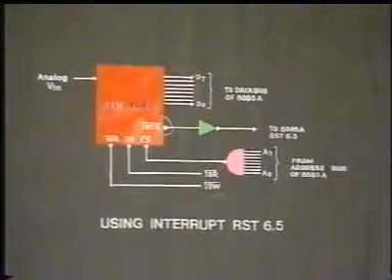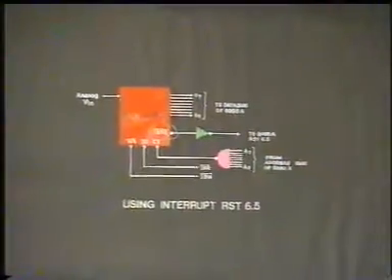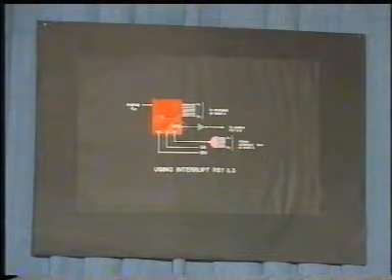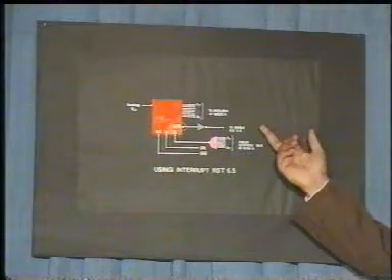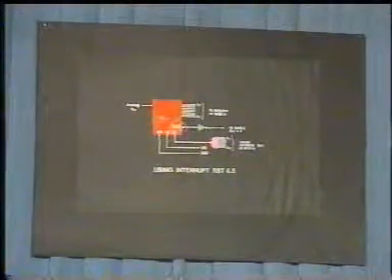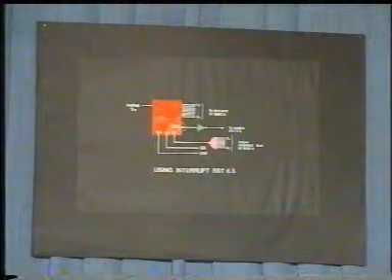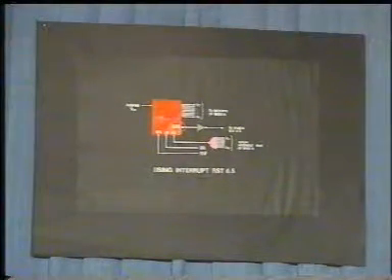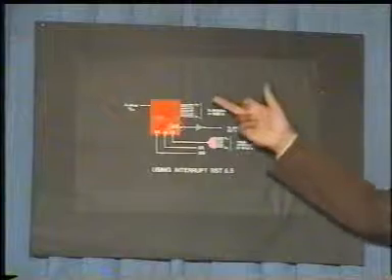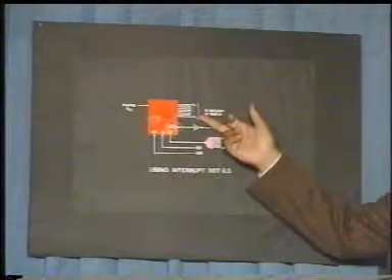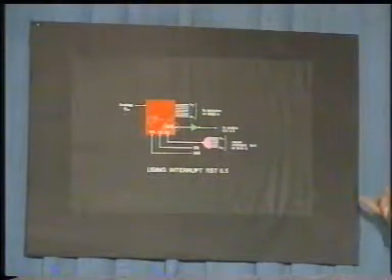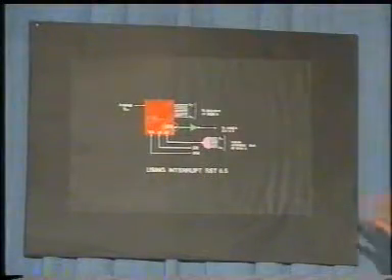If the microprocessor interrupt system is enabled, although we have not discussed the interrupt system as yet in detail, but I'll take it to the minimal level. Whenever the interrupt is recognized, the microprocessor will invoke the interrupt service routine to read the digital sample from here and store it into the memory or anywhere. So this is the hardware requirement. Now let's see the software requirement of this.